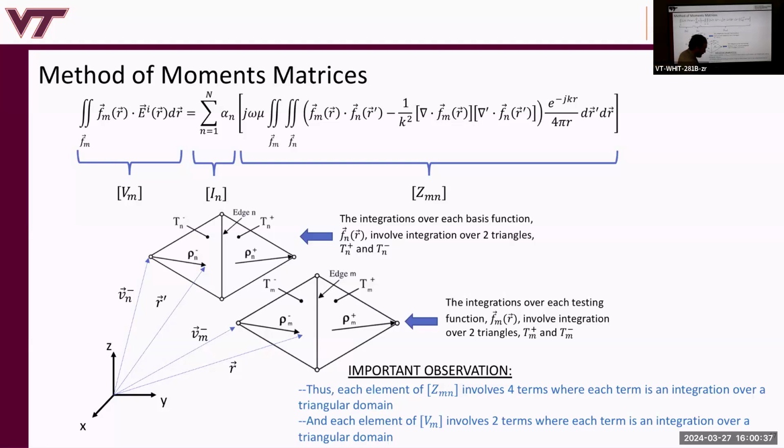So like I said before, if you're able to write the code to do the plate, then you can use any STLs. So you can start to do electromagnetic responses or scattering from arbitrarily shaped objects, anything you can get an STL of. And you can make STLs by going into something like CST or a CAD modeling tool, drawing whatever you want, and then exporting the mesh as an STL.